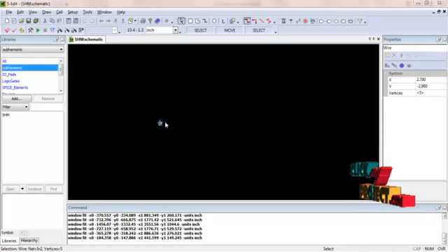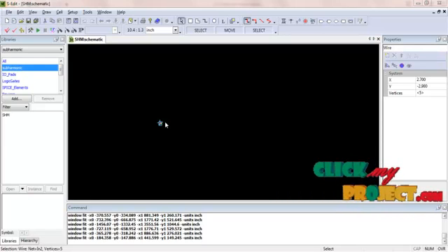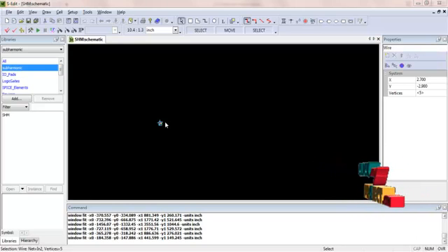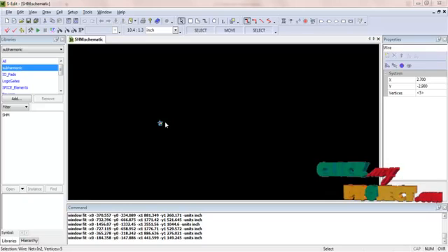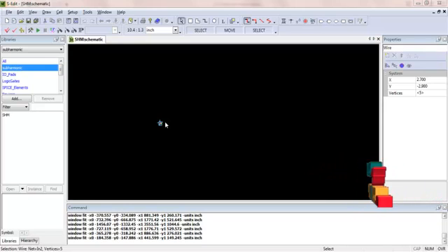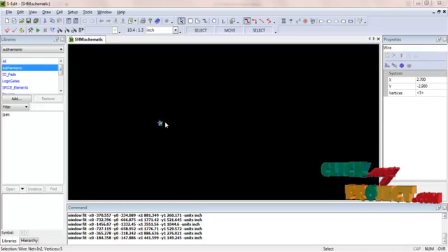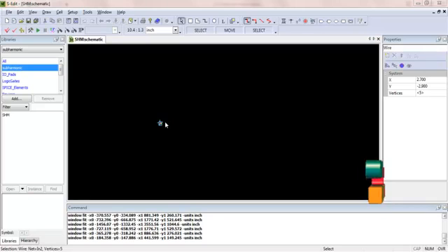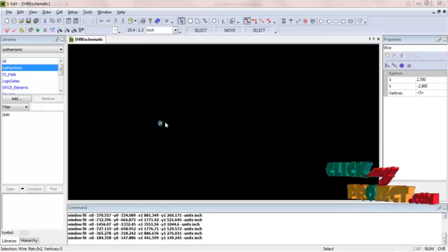The IM2 component generated at the drains of M1A and M2A is applied to a low-pass RC circuit, while the high-frequency RF input signal is applied to a high-pass RC circuit. The output signals in the gate voltage of M1 and M2 are the sum of the high-frequency RF signal and the low-frequency IM2 signal respectively. The circuit consists of the RF transconductance stage, LO switching stage, and the output load stage RL.